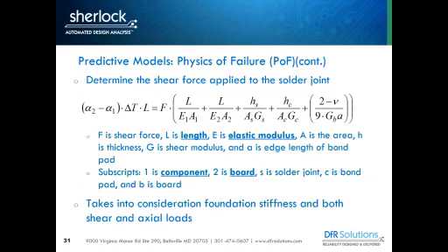Here's just a slight modification where we add stress effects to the solder. Instead of just assuming that the component is infinitely stiff and the board is infinitely stiff, we're actually looking at the stiffness of the board, the stiffness of the component, taking in lead effects, just more complex stiffness type of equations to look at compliance, to look at reducing the load on the component.